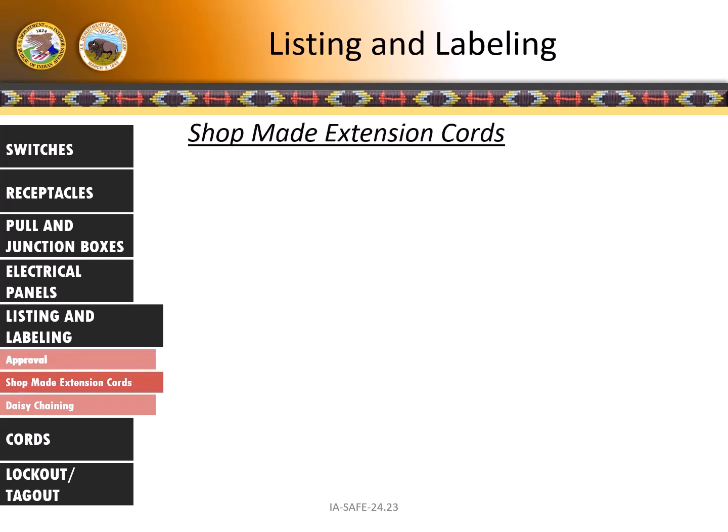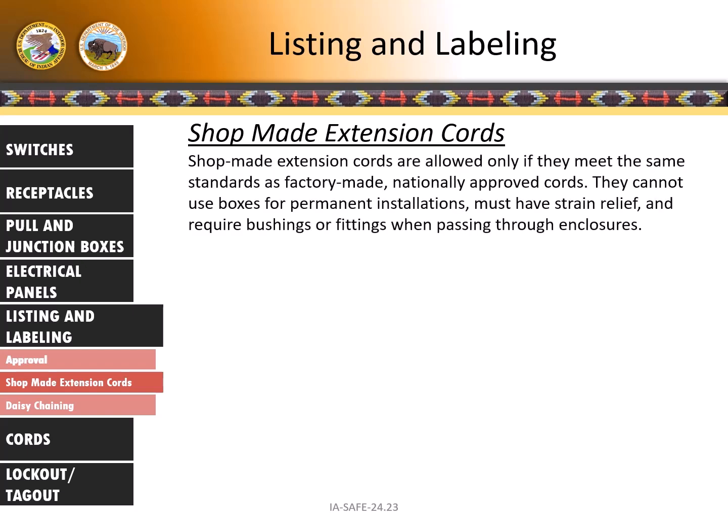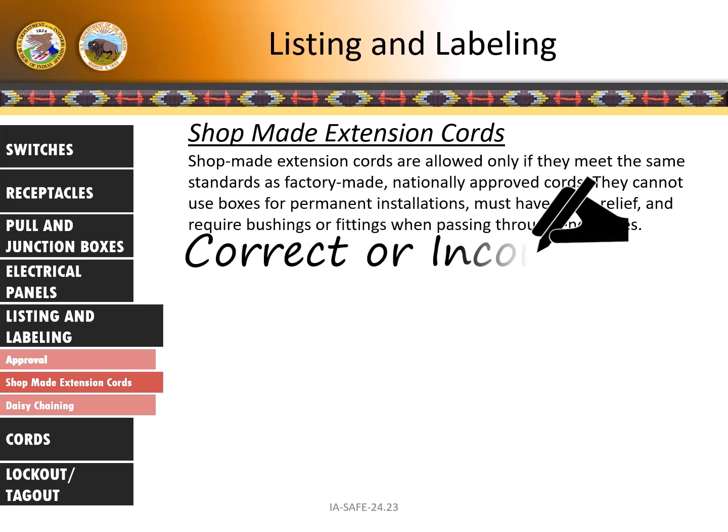Shop-made extension cords. Shop-made extension cords are allowed only if they meet the same standards as factory-made, nationally approved cords. They cannot use boxes for permanent installations, must have strain relief, and require bushings or fittings when passing through enclosures.